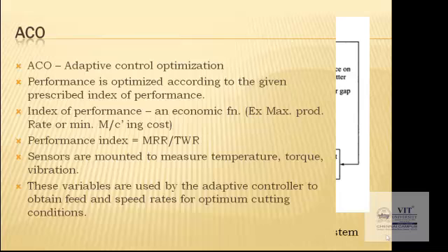Suppose you are doing a job on an aluminium workpiece, you can increase the feed rate and also the speed. That will be optimized according to the material you have used and the parameters that are set. If you are machining mild steel or a highly hardened steel, the depth of cut and feed should be very small. So that should be optimized according to the material. Here, two parameters are calculated based on the tool diameter and the workpiece material, the two values MRR and TWR.